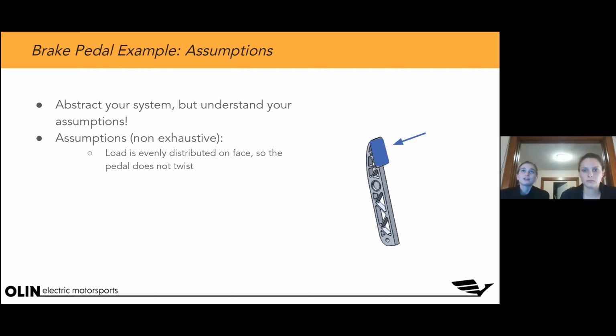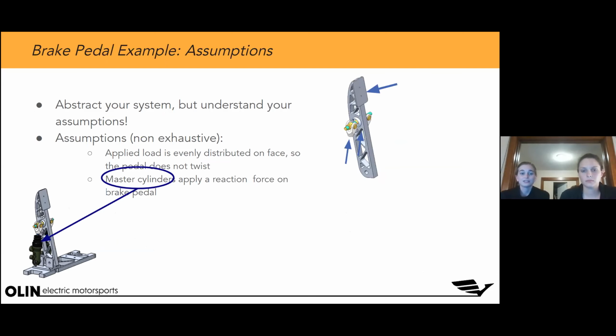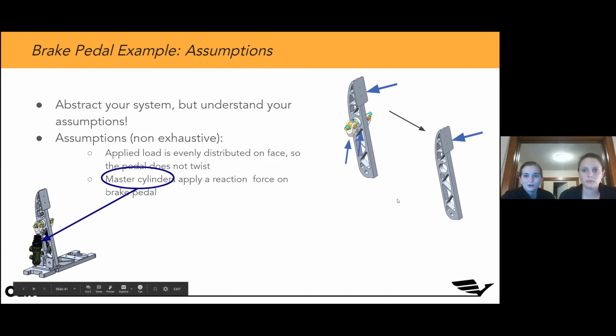We're making this assumption right now as this would be your first case of your analysis, your first step to analyzing this beam on this pedal. Another thing we want to think about now is how we are going to apply the reaction forces from the master cylinder onto that pedal. The master cylinders, if you remember, are holding up that pedal, and they're applying two reaction forces, so we might think, okay, let's apply that load just directly to that face where that bar is.